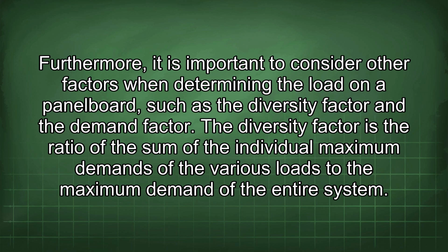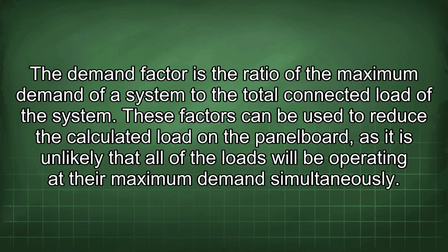The diversity factor is the ratio of the sum of the individual maximum demands of the various loads to the maximum demand of the entire system. The demand factor is the ratio of the maximum demand of a system to the total connected load of the system. These factors can be used to reduce the calculated load on the panel board, as it is unlikely that all of the loads will be operating at their maximum demand simultaneously.